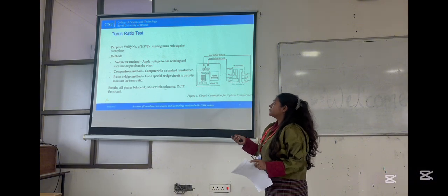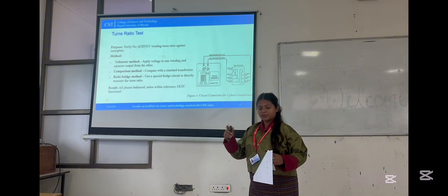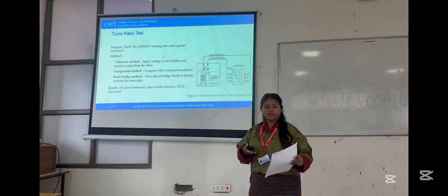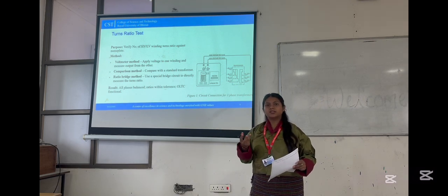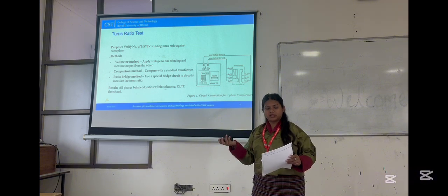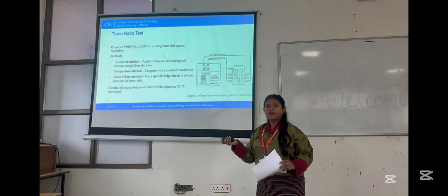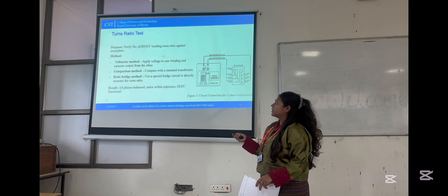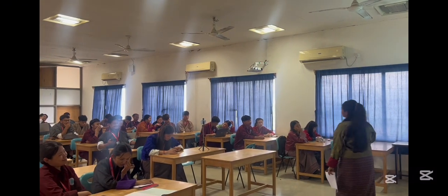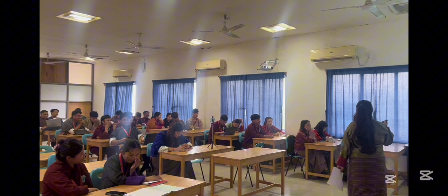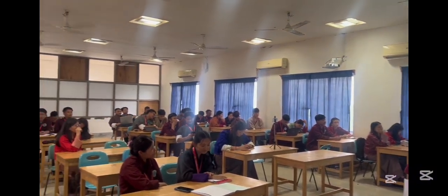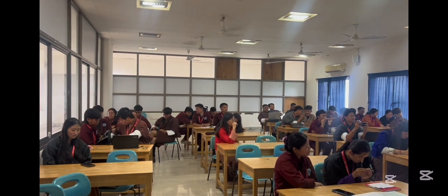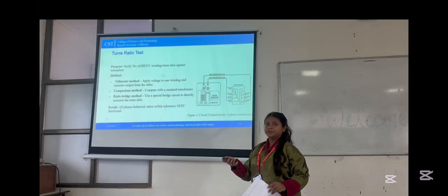In the comparison method, we compare the transformer under test with a standard reference transformer of known and verified turn ratio. The same voltage is applied to both transformers, and the output voltages are compared. This one is used for calibration in labs.